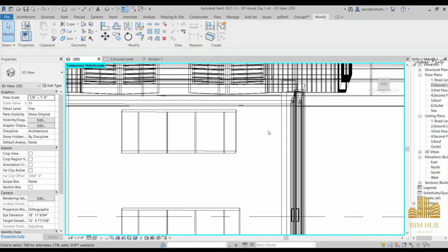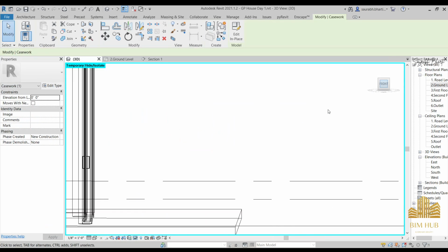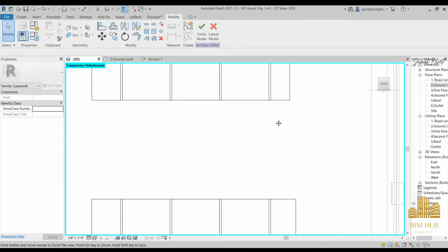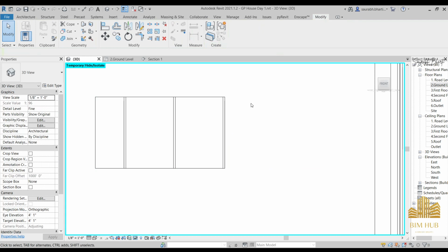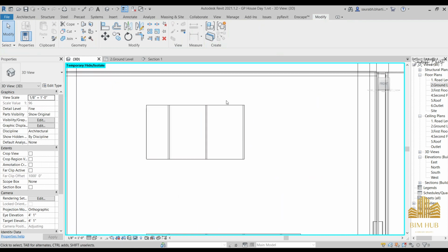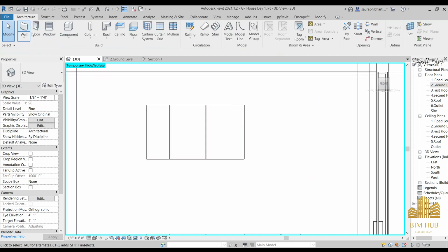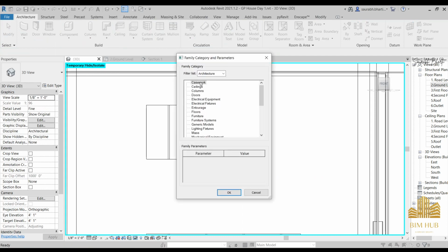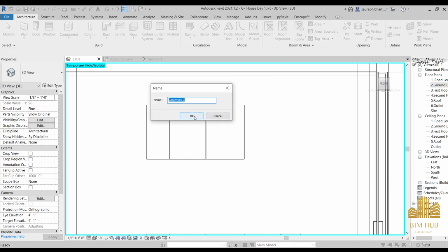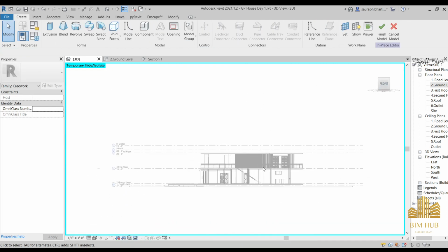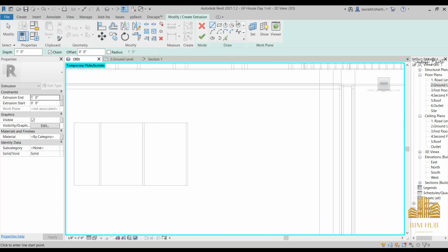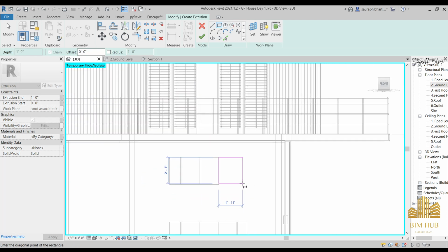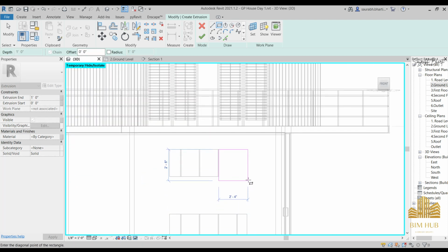So what you can do is, first of all, go to edit and reduce the size of it till here. Finish it. Let us keep it at 3 only. After that, just go to casework once again, component model in place, casework, and in casework just go to the front view, and here just take an extrusion again, and just match it with this one.